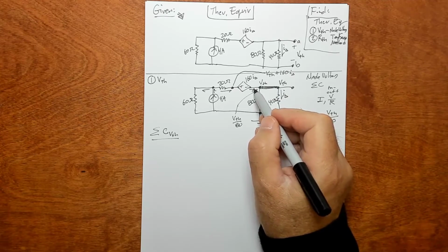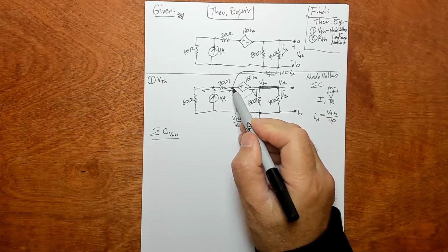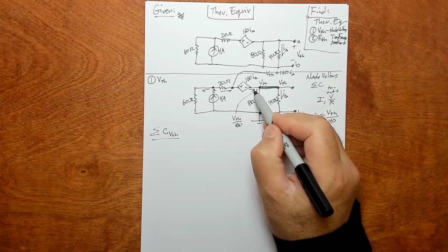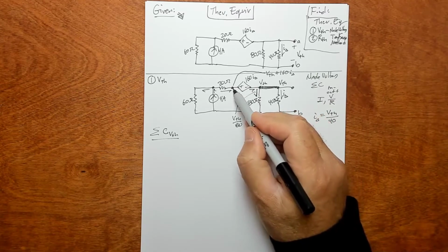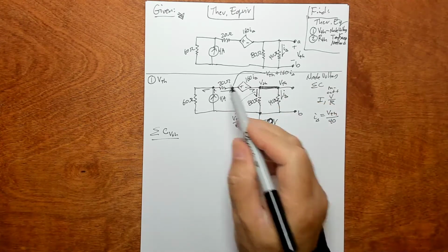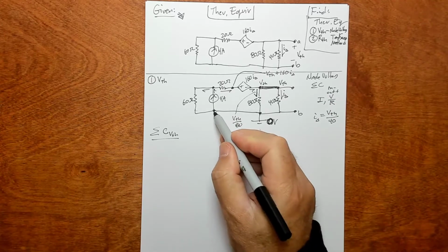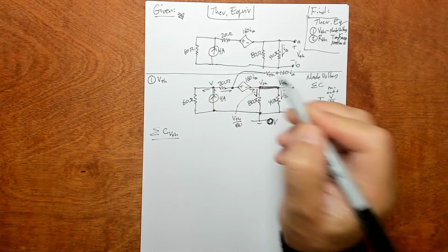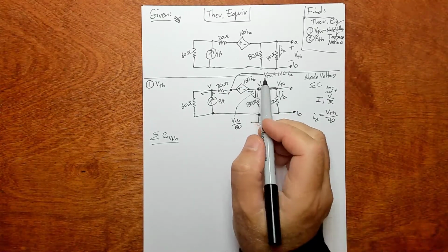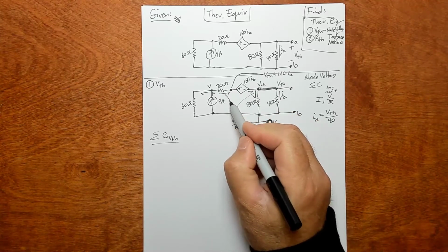Actually, that gives us an expression for this current right here? It doesn't. It just gives us an expression for the voltage at this point. We would need a resistance in here to figure out this current. All we know is the voltage right now. So we have to look around some more, and that's where this other node comes into play. Let's label that node. There's 0 all the way across the bottom, and then we're rising by some voltage V. We'll call that V. Then we can get an expression for this current right here.